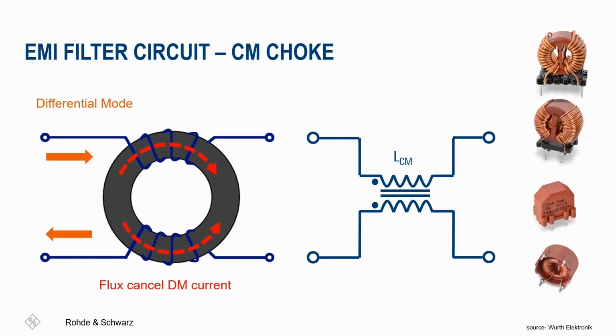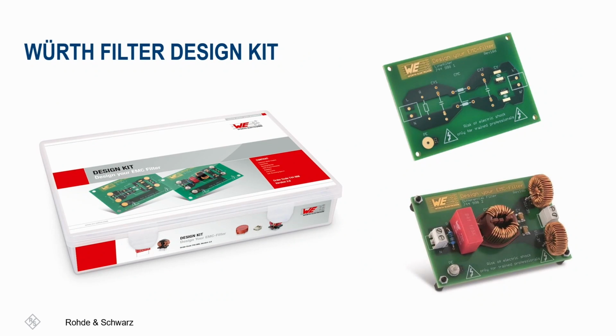In our case study, we will concentrate on assessing the impact of X and Y capacitors. Würth Electronics also offers a specialized filter design kit. It is a wonderful resource for testing the effectiveness of various filters. This kit includes X and Y capacitors, as well as common mode chokes of different sizes and material to tackle different frequency responses.